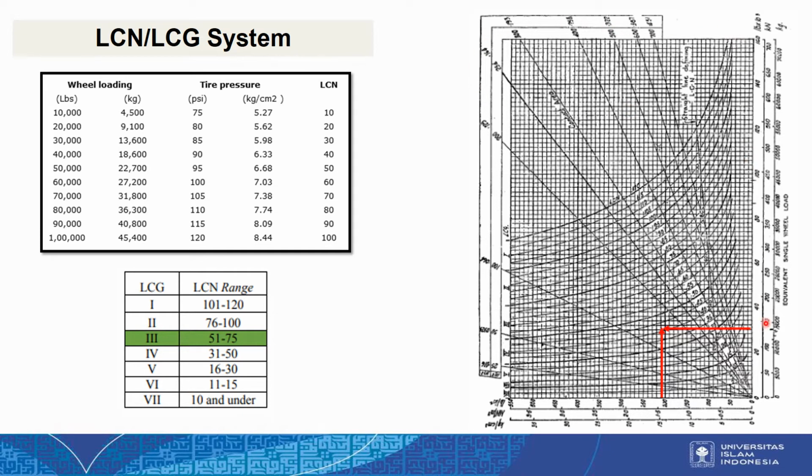So these charts, you can see this is for the equivalent single wheel load. The wheel loading here, we just put it in here. If we want to know the LCN value or the LCN number, this is the graph for LCN value.